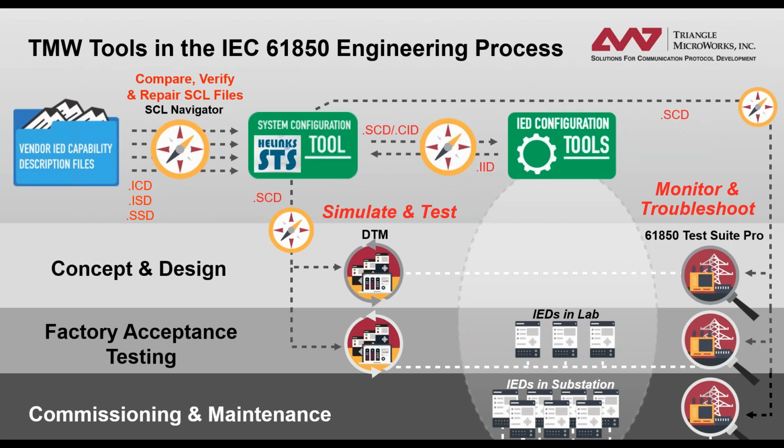If the vendor IED doesn't support the later binding, then typically in the ICD file, we don't have any inputs and xrefs. And then the system tool, according to edition 2.1, can connect it to any logical node where it needs it. So in principle, a trip signal will be connected to the XCBR. So the system tool will add an xref there. And then the IED tool needs, in the post-processing, take that and connect it to its right internal variable. That's basically the two main options as they have been now defined in 2.1.